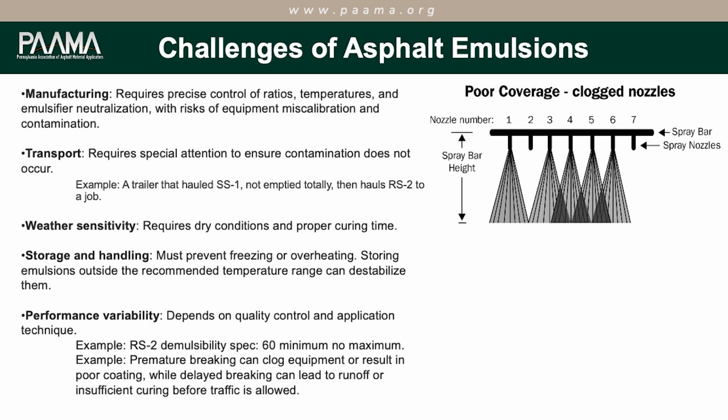Contamination, whether it be in the plant or during transport. So if you have a trailer that had SS1 on it, and then the next day you're hauling RS2 to a job, and that trailer wasn't empty all the way, you mix those two and you're not really going to have an RS or an SS. It's probably going to be somewhere in the middle and likely out of spec, and everybody's unhappy because you're not going to see the set time that you were expecting.